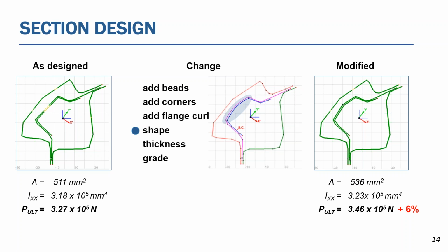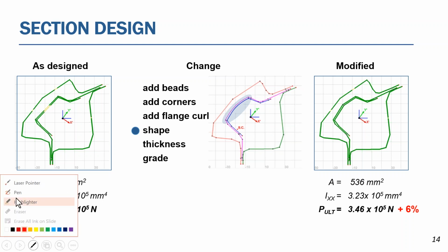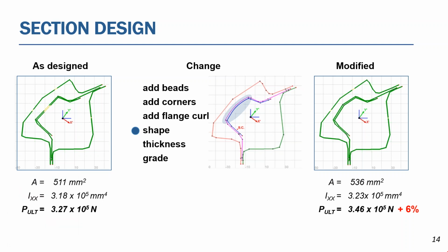Another question here. Can you say a few words about holes or sections not welded, open sections? Yeah, they can be analyzed as well. They tend to be very unstable. If we have, let's see if I can draw a section here, just take that as an arbitrary open section. GAS will compute the nominal properties. Those are the classic area properties.